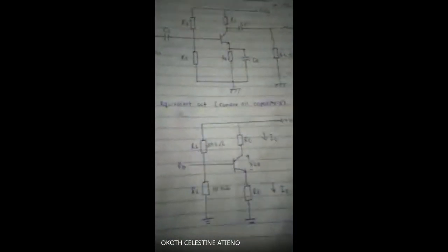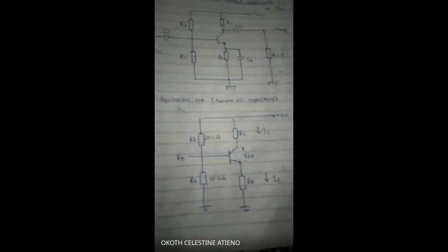I think you guys also remember this from first sem. So let's look for a DC equation. Another thing I want you to note is when you're looking for load line, you want to look for VCE, the output voltage, and IC, the output current.